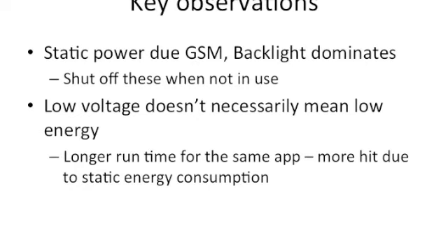It's not necessarily true that running slower will also reduce energy. You could actually end up consuming more energy, and hence there is this notion of a point of optimum energy. There is a speed at which you have to run, which will minimize the overall energy consumption. And we'll discuss that later in the course, in more detail, how you can automatically try to track that point of minimum energy, etc.